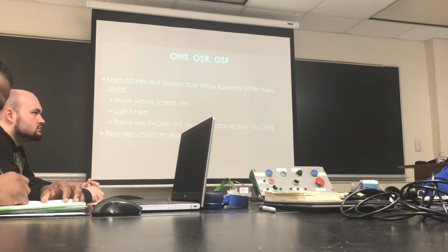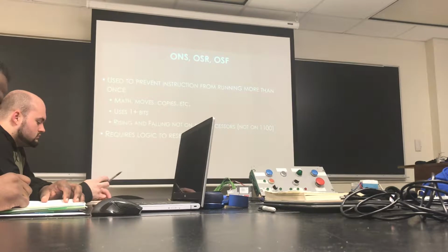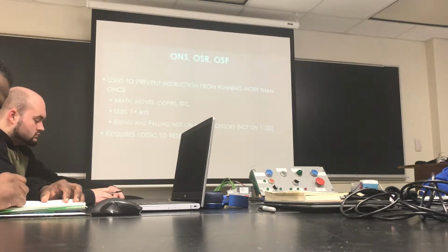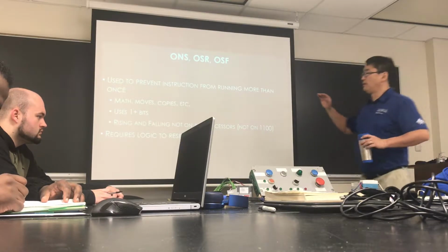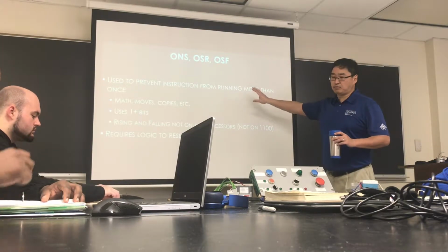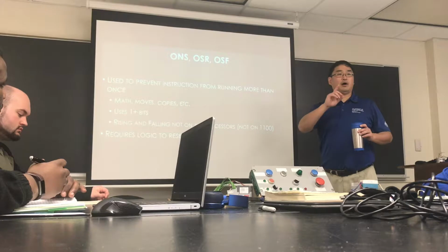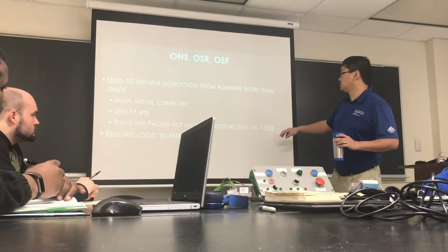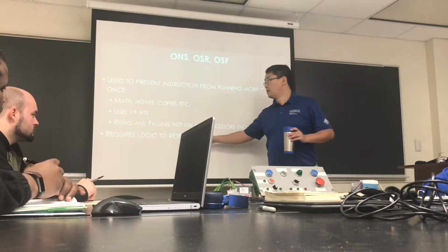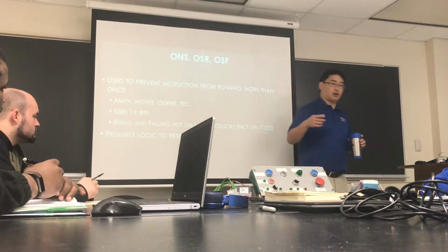One-shot requires a single bit that it handles. It says, hey, what's my state? And it sets it from 0 to 1 automatically. You don't have to do anything with it. It handles it itself, but it lets or prevents the processor from doing that rung more than one scan. The one thing you do have to do is you have to reset the rung, because the way the